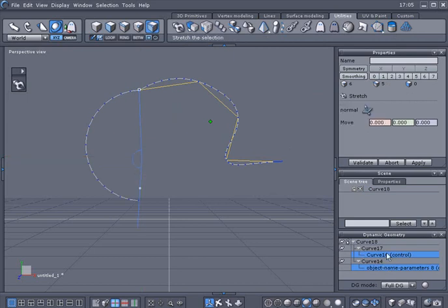Now down here, as you can see, I've got both lines selected, and if you double click on these, you just get one selected. If you want to just edit one line, if you double click, nothing's going to happen. It's just going to sit there. Move your cursor over to the left. There's a little slash mark, and I'm just going to click here once. As you can see, now I can just edit this line here.